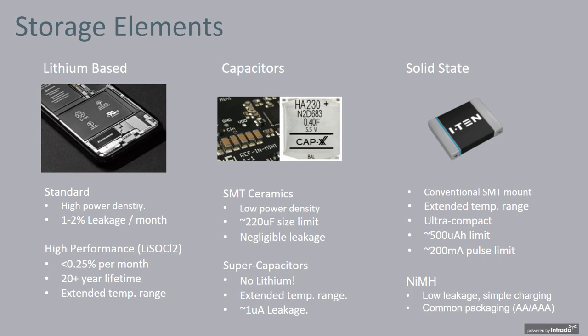Another cool battery technology is solid state. It's going to have similar functionality to a super cap where you could run for those days or a week, but it's going to be ultra compact. And it comes in a surface mount package, which is very nice. They have pulse currents that can drive RF modules, RF radios, sensors. So that could be a really nice solution if your application requires that.